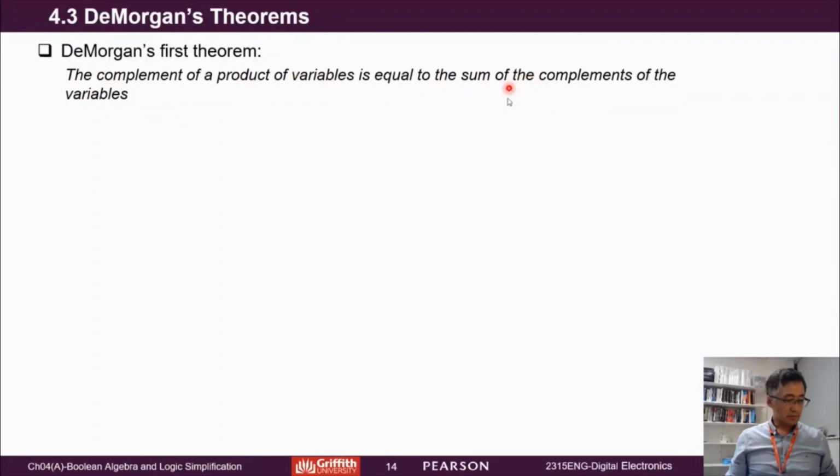Let's use a Boolean expression to describe it. It will be much easier. So we have two variables, right? Two variables times together, and we have an overall bar. The bar means inversion, not. So we have a long bar, an overall bar, over x times y.